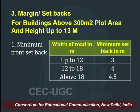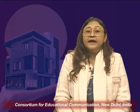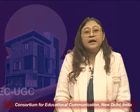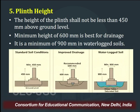These are all values I am discussing right now for the residential building. When the building usage changes, for example, if it becomes commercial, the setbacks totally change depending upon the size of the plot and the width of the road. Moving ahead, for buildings above 300 square meter in residential and height up to 13 meter, the minimum rear setback is 3 meter and the minimum side setback again will depend upon the size of the plot. So, on these aspects, the size of the area and the length of the margin is taken care of.